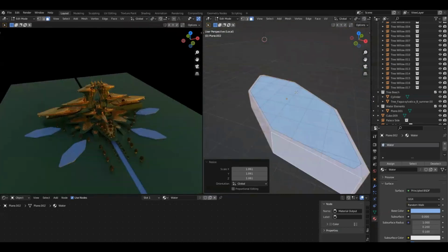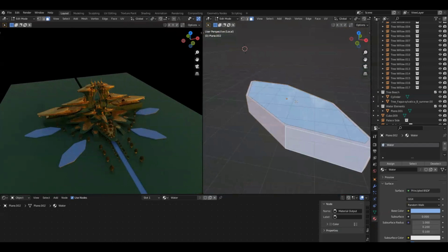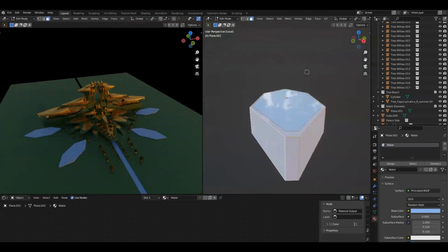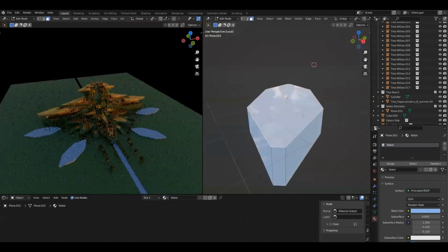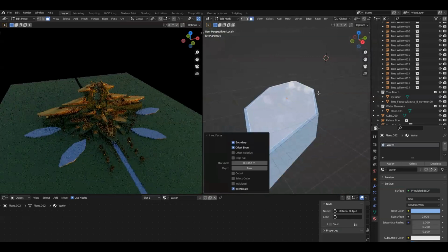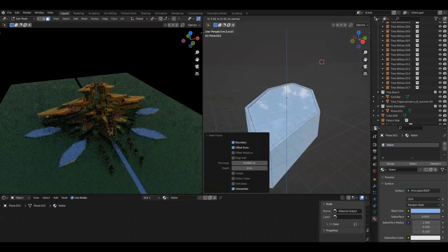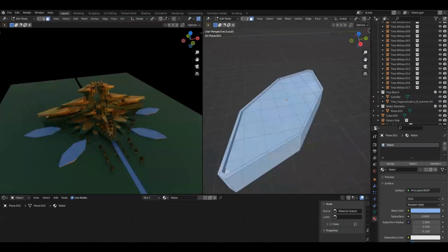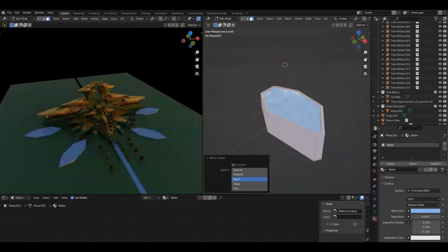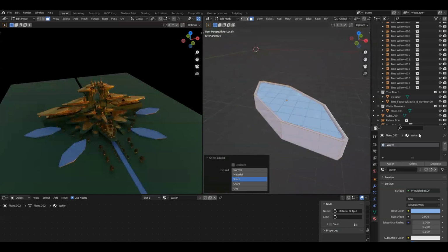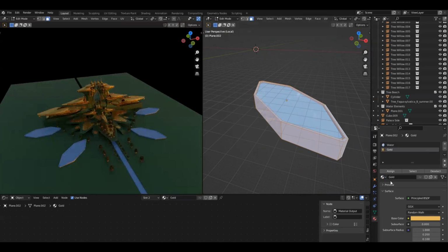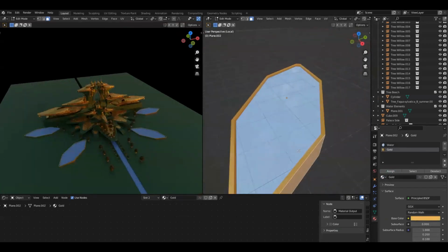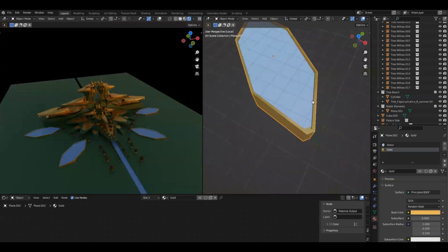And I just went into isolated mode, by the way, with the question mark key. And all I want to do here is move it up on the z-axis a little bit, then select the top face, inset just by a little bit, and then extrude downward so it goes through the water. And now this extra element that we just created, let's hit L to select that. And let's create a new slot in this object and make that slot gold. And then assign that new slot to those faces. There we go. I think that's what I was looking for.